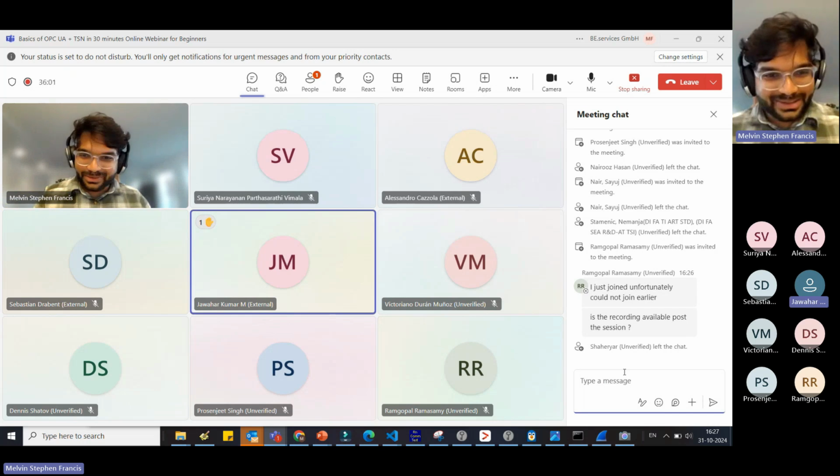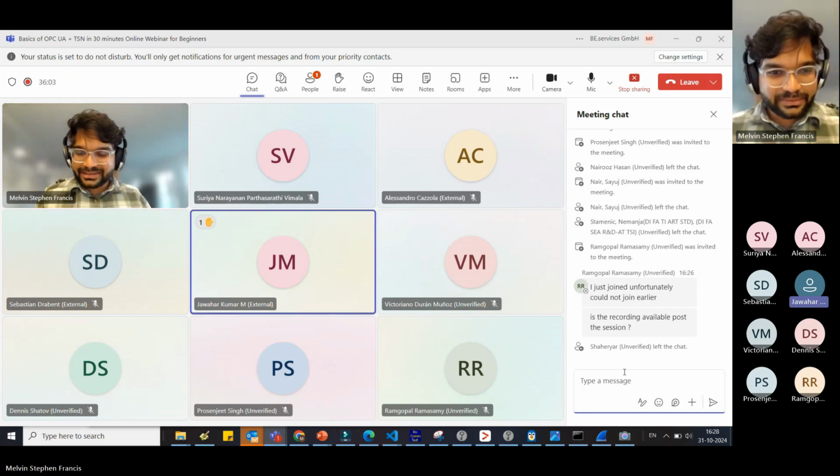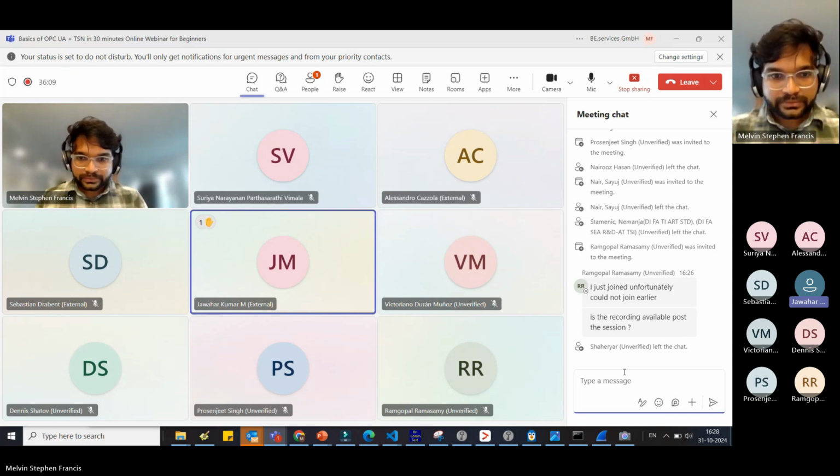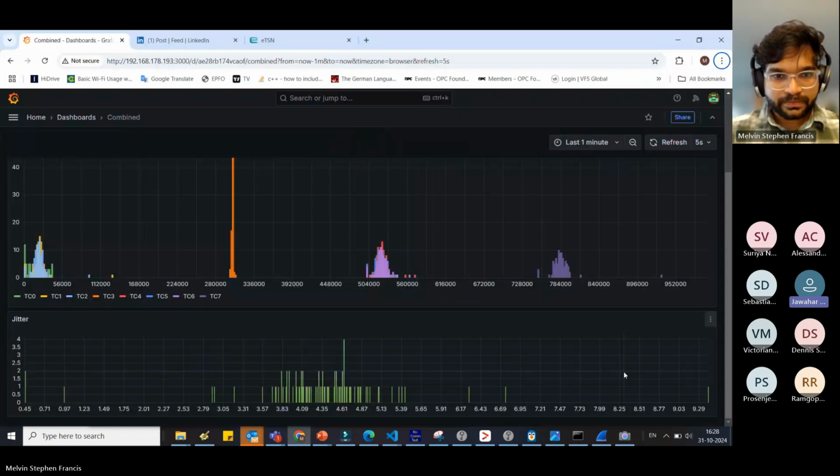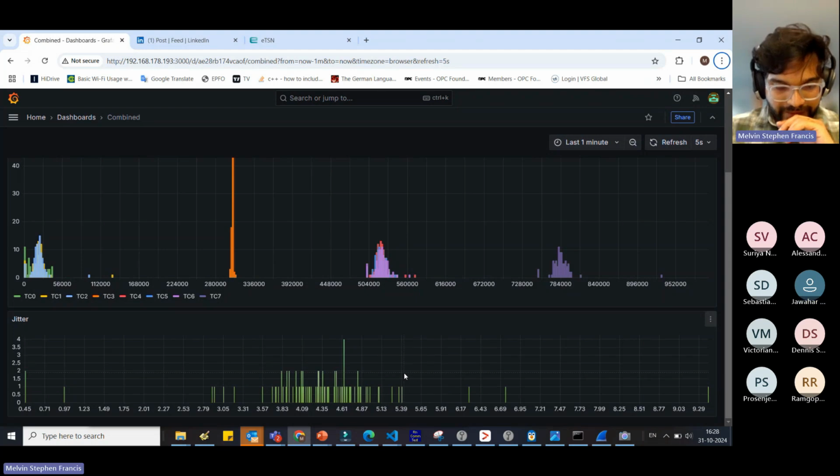Point number two. I've noticed one of the things you said is the time series, the scheduling perspective. But from an industrial applications point of view, some modules might want to send more critical data which cannot wait until the token system is passed to them. You touched upon QoS, quality of service.